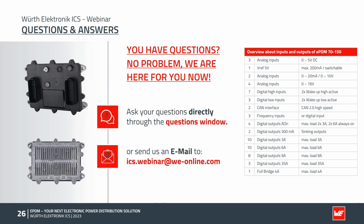Yeah, all right. Already some people are asking. Can you name an example of what vehicle functionalities a 150 amp output can be used for? There is indeed not a 150 ampere output. It's the summary, the gathering of all the outputs, and we can manage up to 150 ampere in total current consumption of the device, and that's what the main 150 amps at 70 degrees or 120 amps at 85 degrees means.